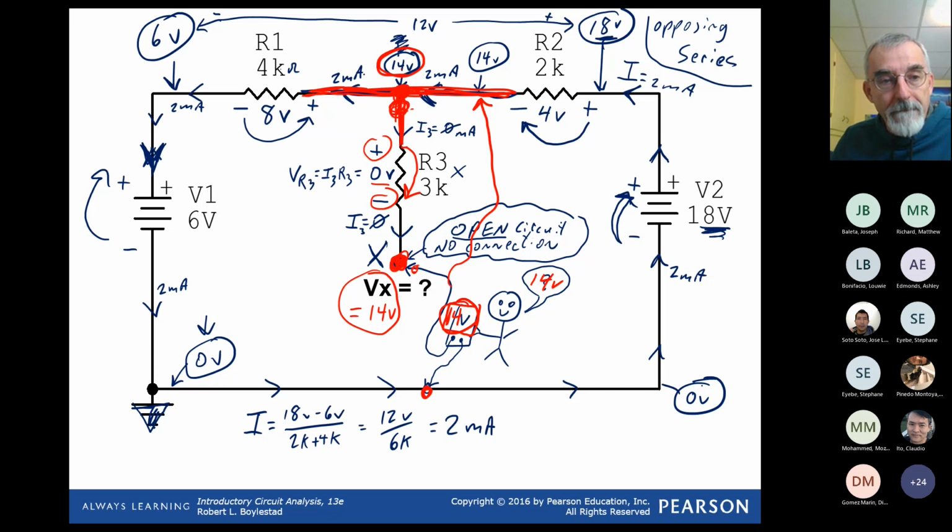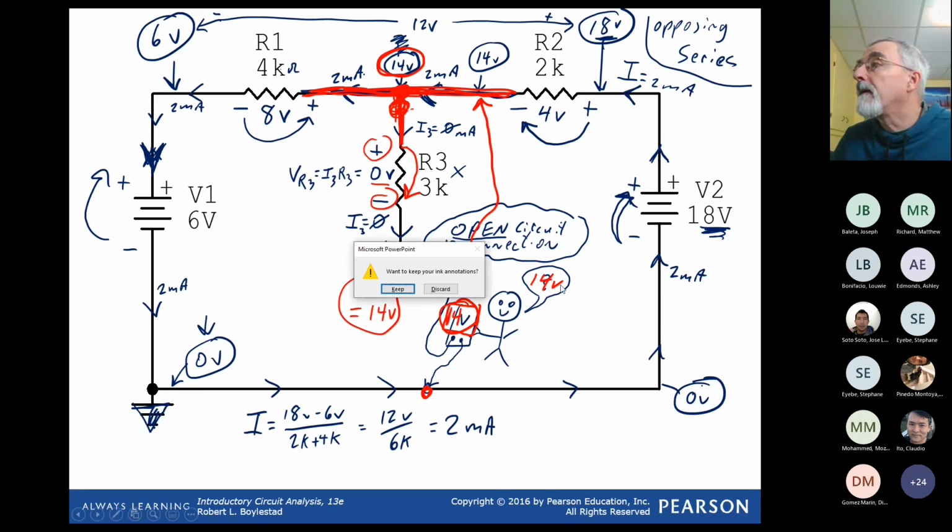One question, Ray. Yes. When I connect the voltmeter, the current doesn't start to flow at this point? No. Because the multimeter is a good multimeter and it's set to voltage, it has a resistance of infinity. It's a good question. It has a resistance of infinity. Let's